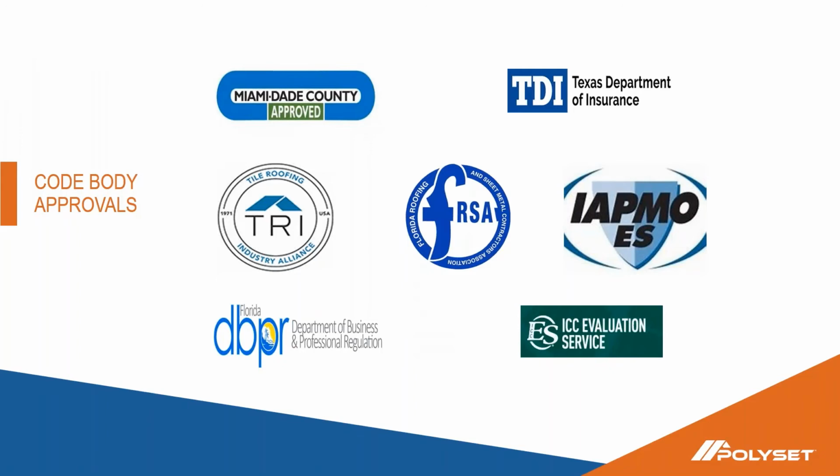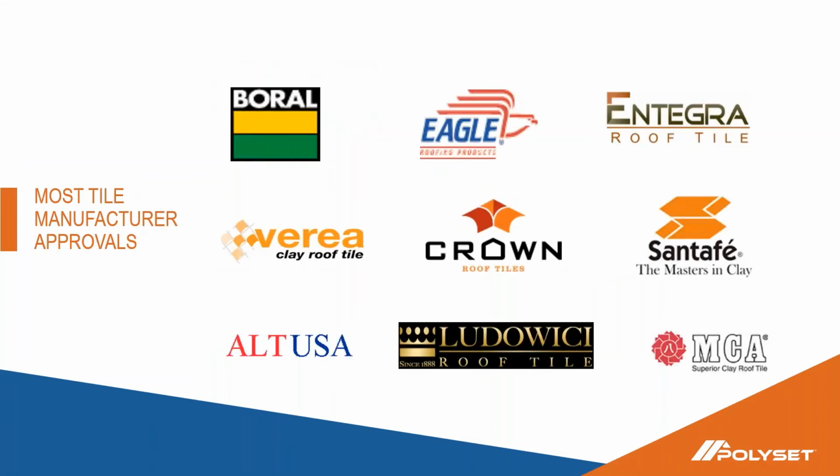It's also important to make sure that the adhesive manufacturers are listed in the areas that you are working. Make sure that they have the correct code body approvals. And also, depending on where the job is located, you might need to look at the tile manufacturers' NOAs to make sure that adhesive manufacturer is listed as a component to be used with the tile.